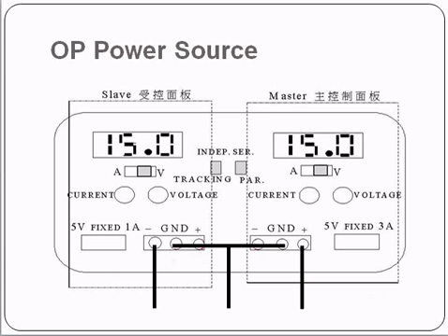To provide the positive 15 volts and minus 15 volts, we'll use the power supply. Recall from the first lab of this course, we have to connect the master and slave as the figure shown. Because our op-amp is very delicate, we'll need to limit the current, otherwise the op-amp will burn. Limit the current to 0.02 ampere to avoid tragedy.